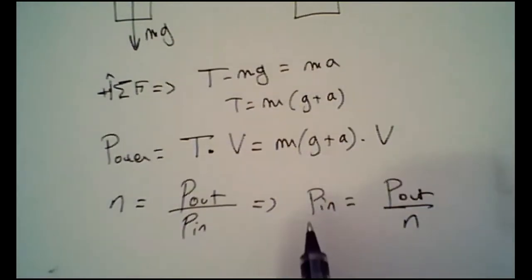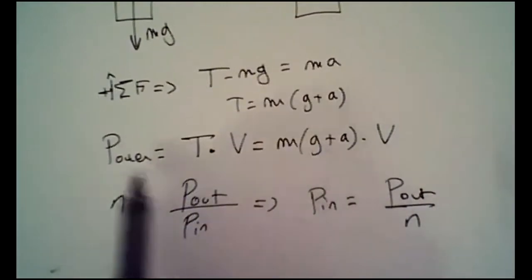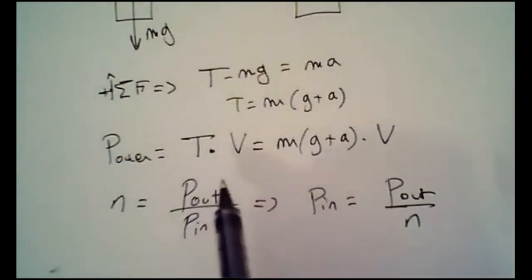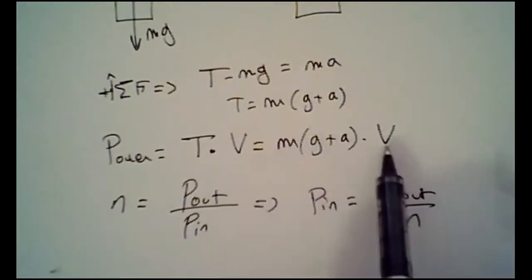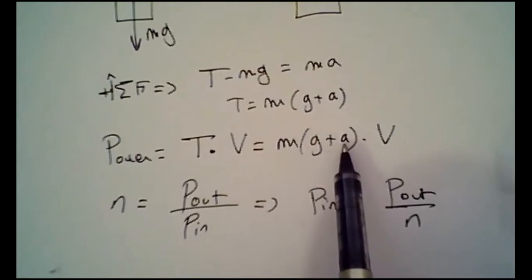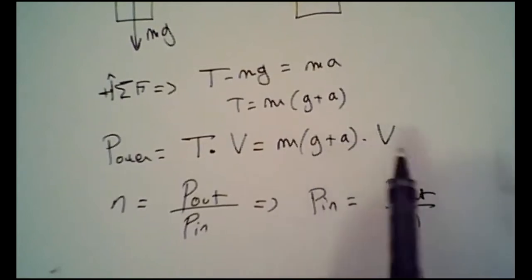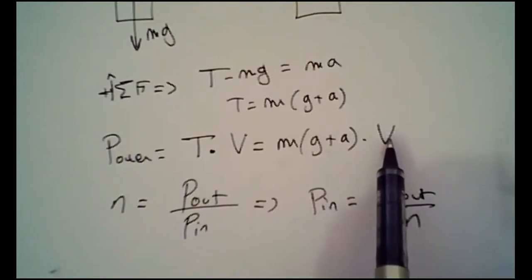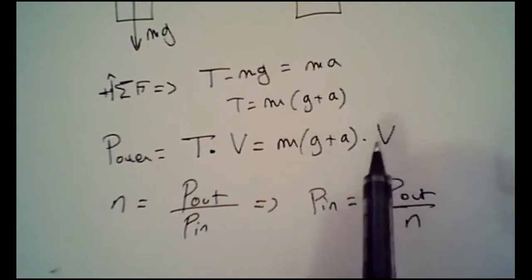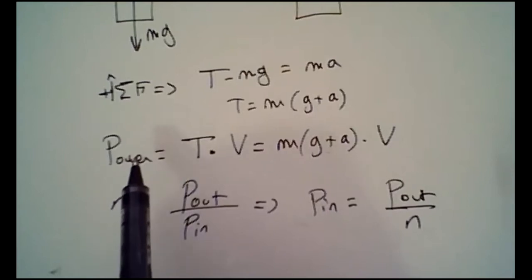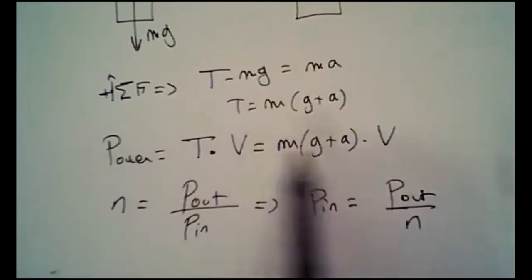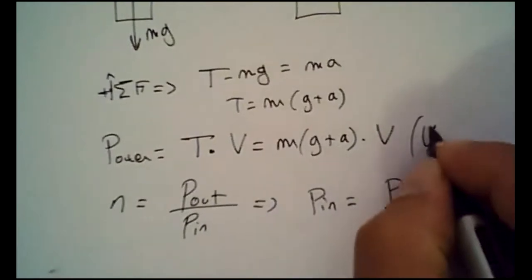And all these are rated mainly by their power. So in the case of our elevator, let's say we obtain the instantaneous power, we can also obtain the maximum power. The maximum power will occur at acceleration, when the acceleration is greatest at startup, at that velocity, right? So you can calculate the maximum power, and the motor that you are getting has to have a power that is greater than your maximum power, all right? And ultimately the units of this will be in watts, right?